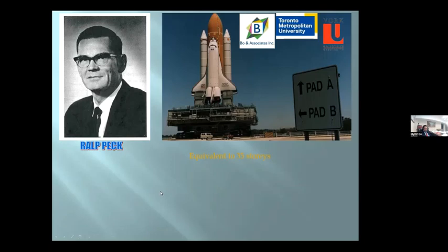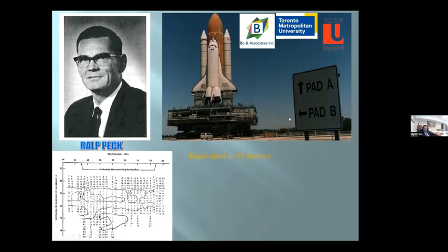Unfortunately, that launching pad was connected to the land by a causeway. And unfortunately, this causeway was underlain by a very loose deposit of silt, which is an SPT group 0 to 1, very loose. By passing this heavy equipment with the static load and dynamic forces, this causeway could collapse.